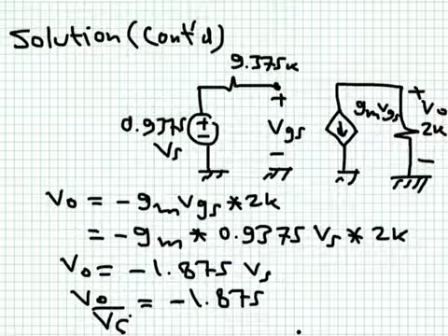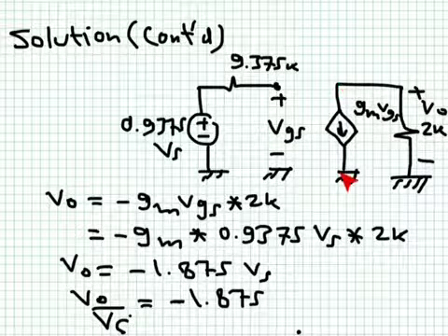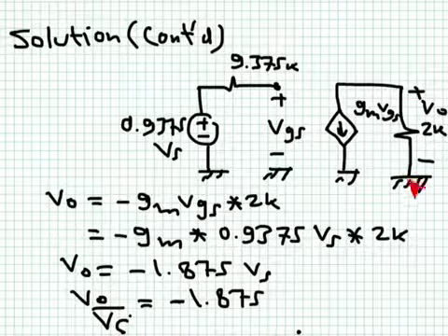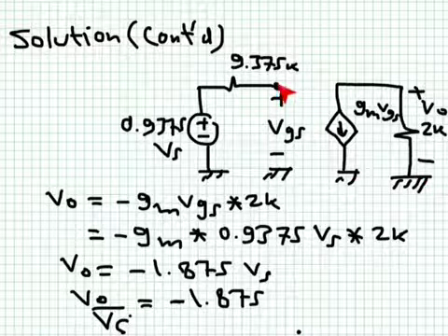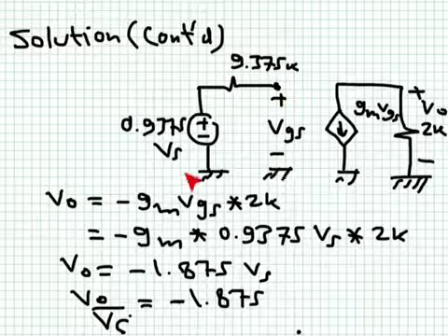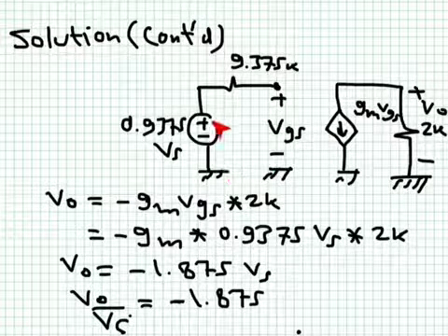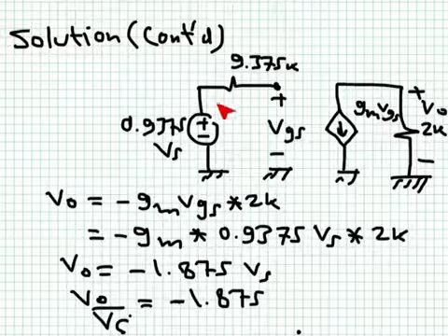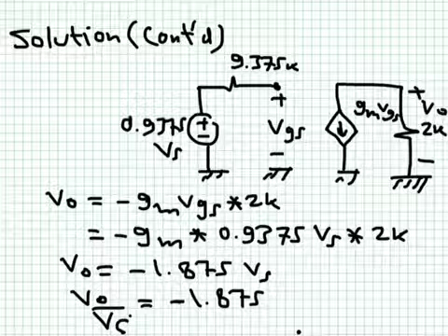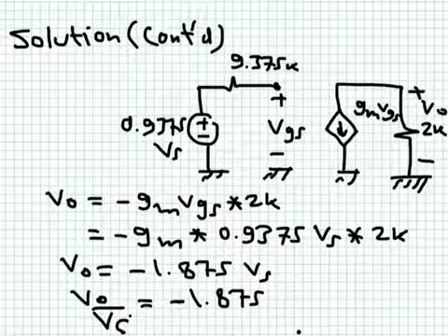So this is how the circuit looks after you make your simplification. This is the drain, this is the source, this is ground. The source is ground here. VGS is the voltage between the gate and the source, which is ground. So this is VGS, and this is my input stage. Of course, because the gate is open circuit, the AC source effectively sees an open circuit. So 93% of the voltage is what's being drawn to this part.